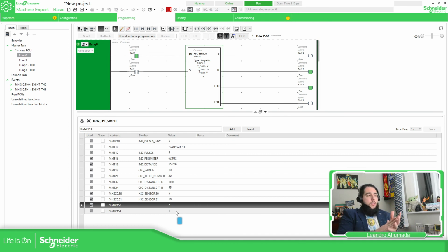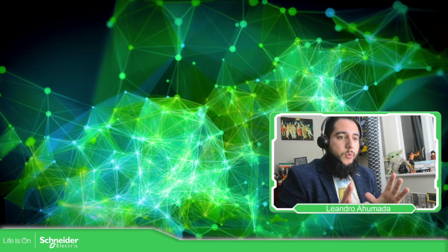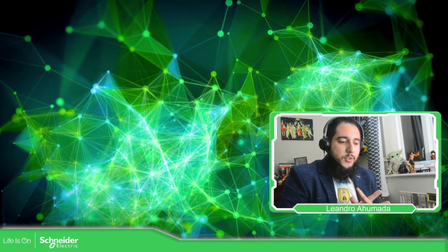So this is how you can work with the high-speed counter in single phase. You just need to use, for example, an encoder or something that varies very fast, up to 100 kilohertz, and then you can work with this function block that we have seen today. So this is it for the high-speed counter as single.